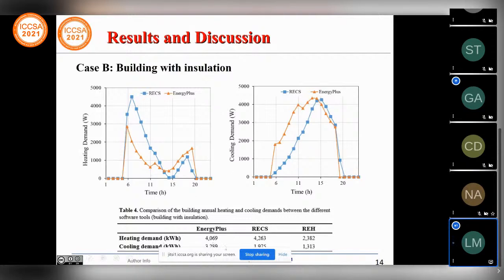in the case of Energy Plus and the RECS, which was expected, because when you insulate a building, you have to shade the windows facing south in particular. Otherwise, you will have overheating, and you get better results in winter and less gains of heat in summer through the walls, but then you get lots of sun radiation, and it doesn't compensate for the insulation.